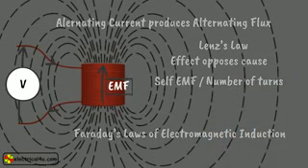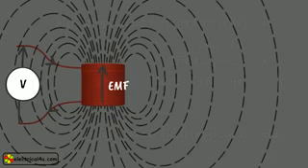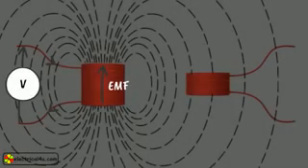We have said that there is another winding in the most basic transformer, but till now we have not discussed it. Now we are coming to second winding in the transformer. Supposing one separate winding is brought nearer to the first winding, then this second winding gets linked with a portion of varying flux of first winding. Due to this varying flux linkage, there will also be an induced EMF across it.